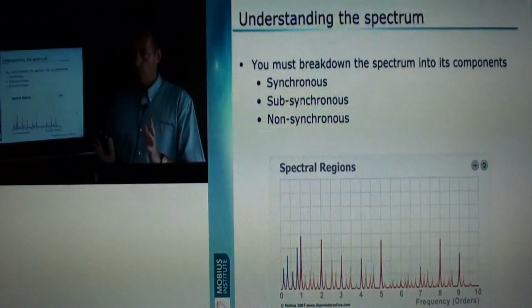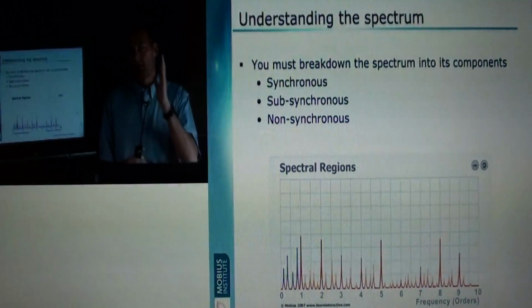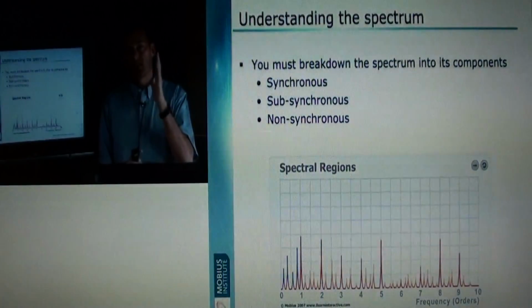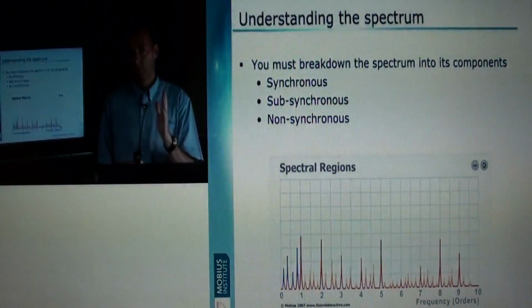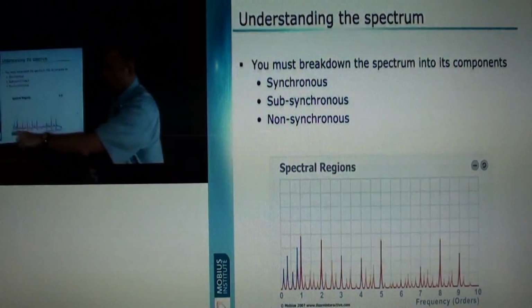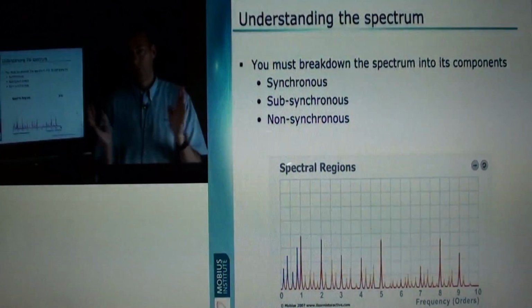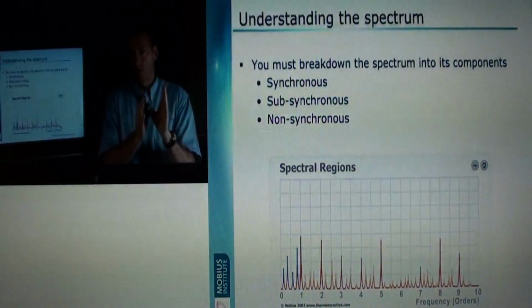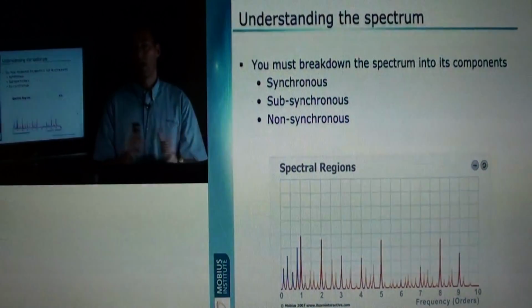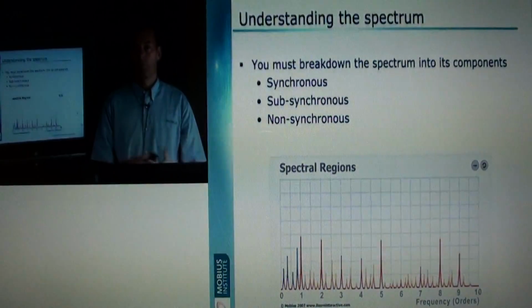The key to it is being organised with your vibration analysis. It's looking at your spectrum and accurately detecting which one is the 1x peak, what is your running speed, and whether you then normalise the graph as I have here, whether you mark off the graph as 1 times running speed, 2 times, 3 times, 4 times, whether you do that or not is totally up to you.